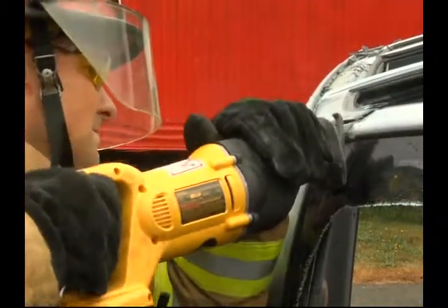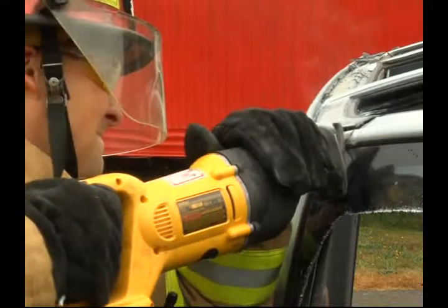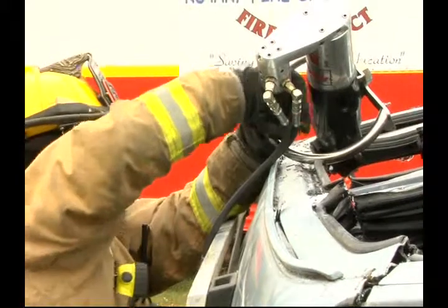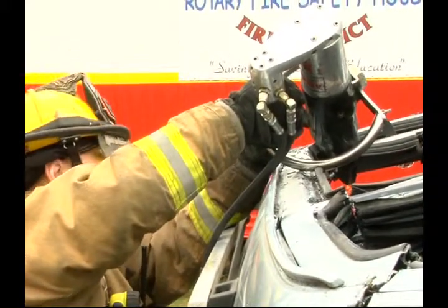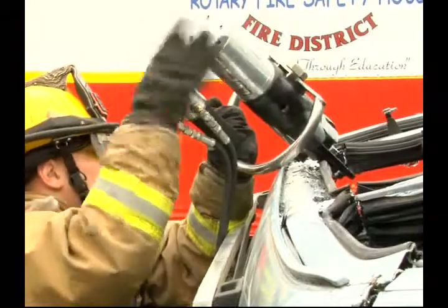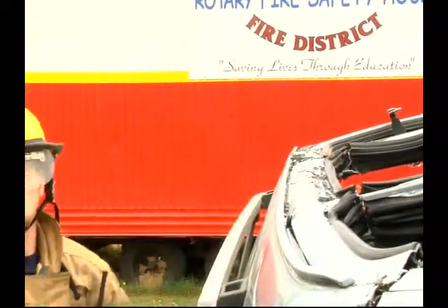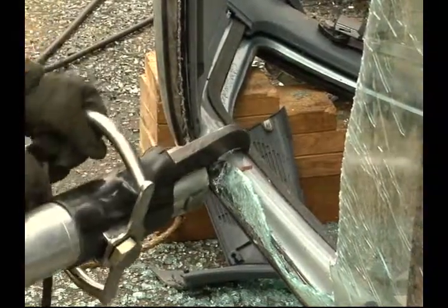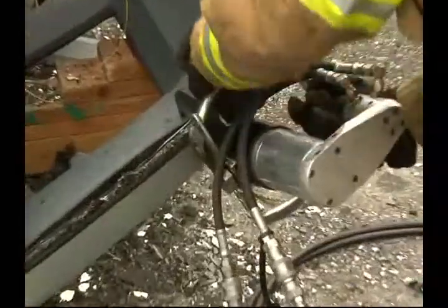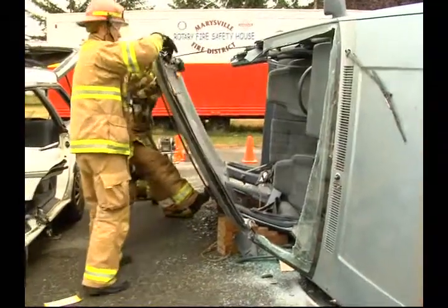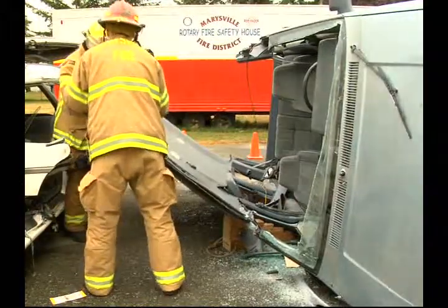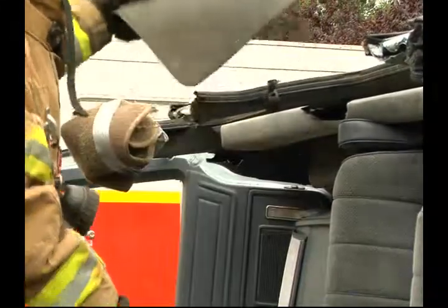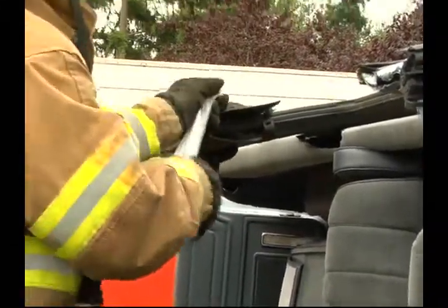Next, cut the high side roof pillars A, B, C, and D at the roof line. Try to make your cut as flush with the roof as possible, so that when the roof is peeled down, the remaining pillars will not protrude into the patient work area. Once you have made the high side pillar cuts, make 2 relief cuts, one at the bottom of the A pillar, and the second at the bottom of the C or D pillars. Finally, pull and fold the entire roof structure down, laying it on the ground. Be sure you implement sharps protection on any exposed areas, both high and low, as you continue with the rescue.